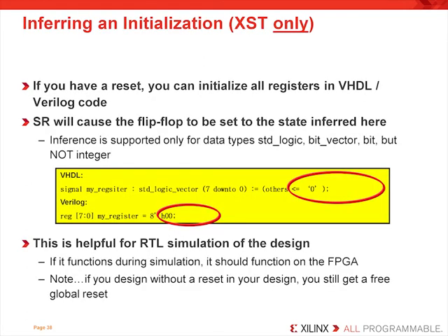This slide demonstrates what we mean by initialization and shows you how we recommend you code for it in your HDL. The set reset will cause the flip-flop to be set to the state inferred here. But note that inference is supported only for standard logic, bit vector, and bit data types. The integer data type cannot infer a reset. As you can see in this case, we're using the when others to define the state of each flip-flop in remaining conditions when it is not defined, and in our case, we care about the initial condition.